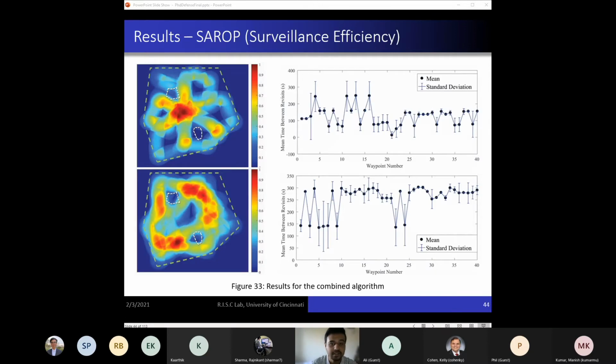The essence of the area coverage algorithm is captured comprehensively through this visualization. The top row corresponds to the segmented search scenario. We see that UAVs route through the local subsections of the map in the segmented search. Even though this improves the fuel efficiency, that comes at the cost of allowing minimum overlap with individual segments. So this is not a very great technique for strict surveillance. The bottom row plot corresponds to the strict surveillance case. We assign 8 priority waypoints on the edges that are required to be visited by 2 UAVs per their individual tours.